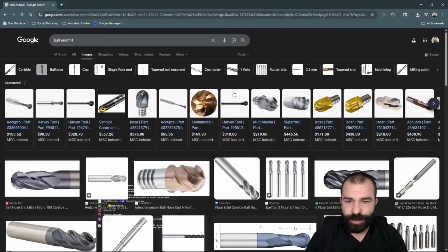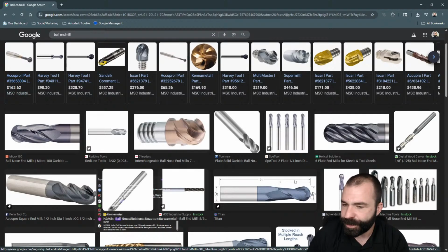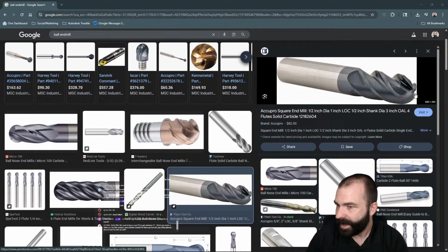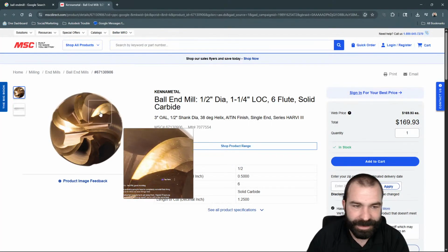Now, the issue is when utilizing basically any end mill, right? So with a 2-flute end mill, both flutes technically go to center. But if we start to look at something like this guy right here, I guess I should make sure that my OBS is showing you guys this. If we look at this tool here, and you look at the very, very tip of the tool, there may only be one flute to center. So even though you have 4 flutes, when you're cutting below, let's say 5 degrees, you actually only have 1 flute as a whole.